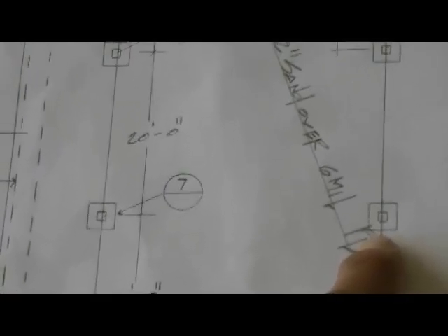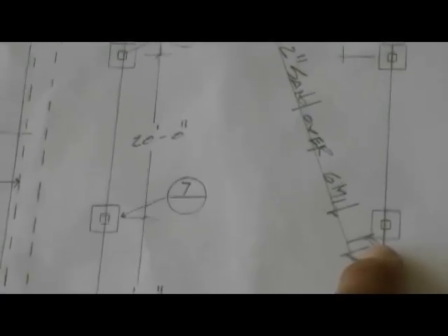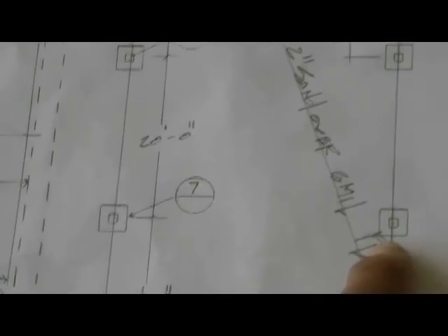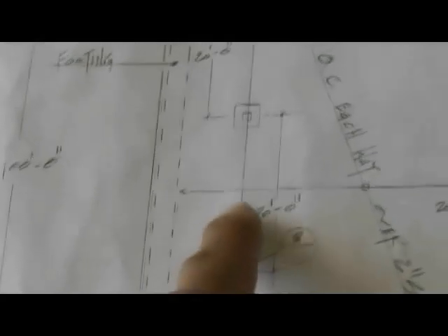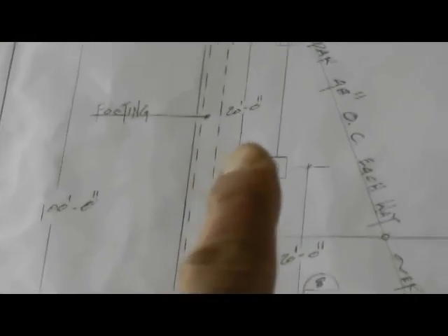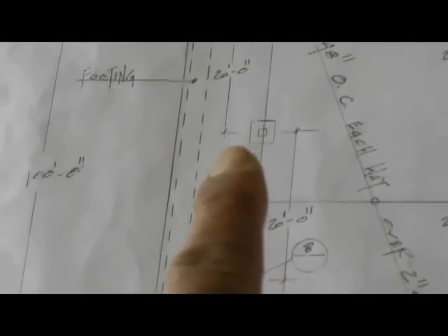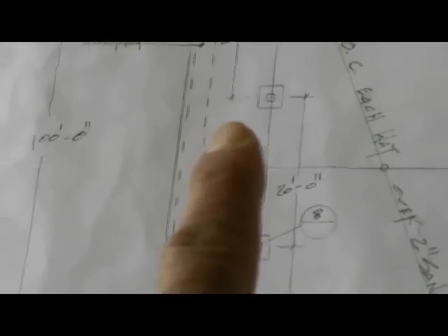We need to control the live weight that's going to be up there by supporting them with these posts. So this post, this post, this post, and so forth are going to be erected up to the bottom, and I'm going to show you another page of the continuous purlin that's going to run this way, mid-span of the roof rafters.